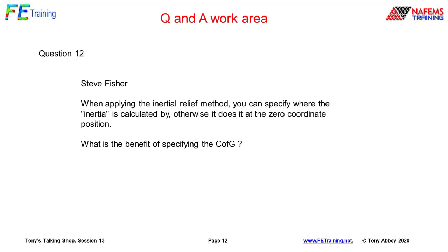As I mentioned, the inertial relief method is a little bit subtle, how you're actually going to eliminate the rigid body modes. You can define those, as I showed an analogy there, like with a 3-2-1 method, or you can allow the system to do it for you. I think I had a little picture in there to show it.